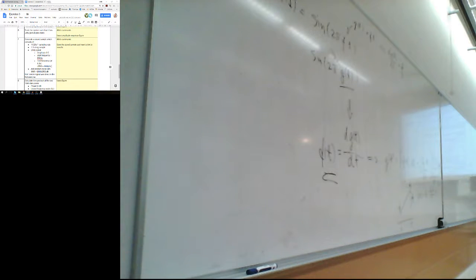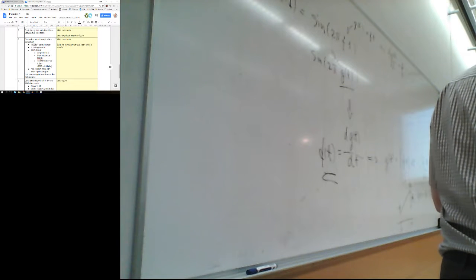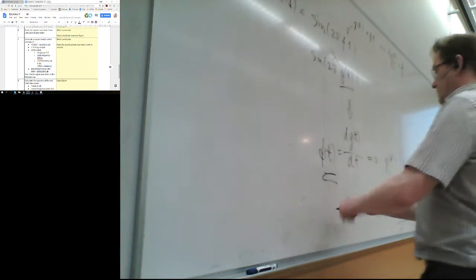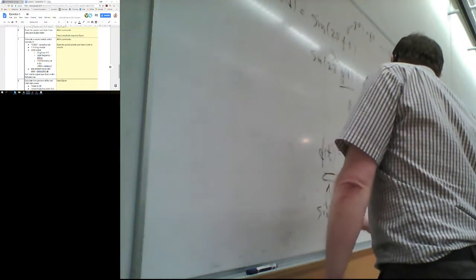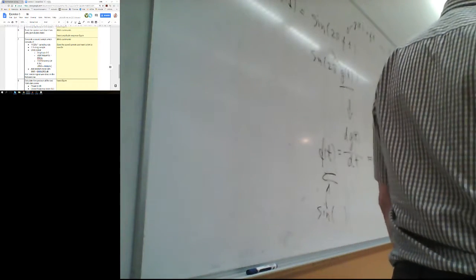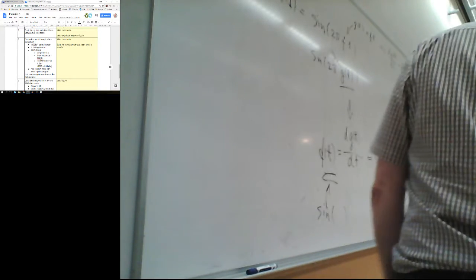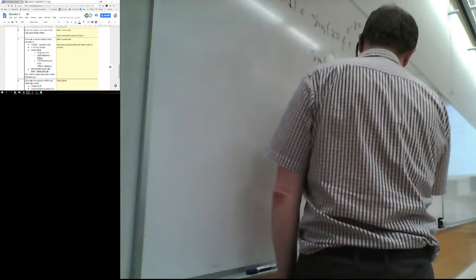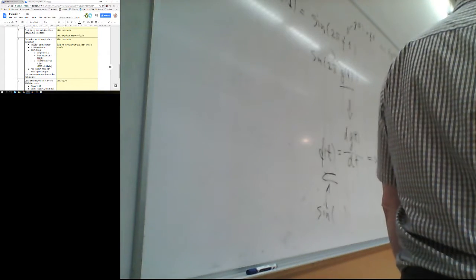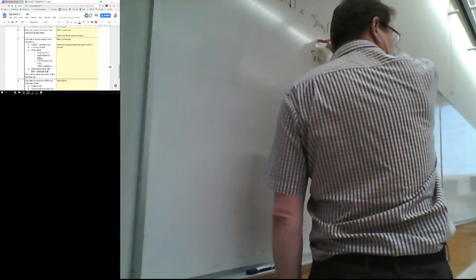But if you want to generate any signal in a MATLAB environment, you would actually plug in the modulating frequency, the frequency what you want, on g(t), and then do numerical integration, a cumulative numerical integration, and then plug that one inside of sine.